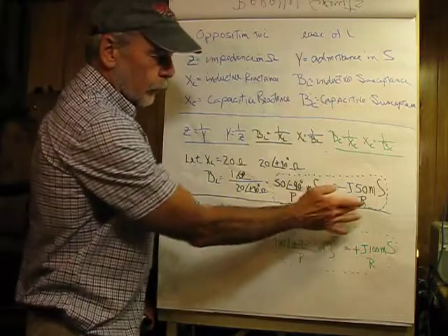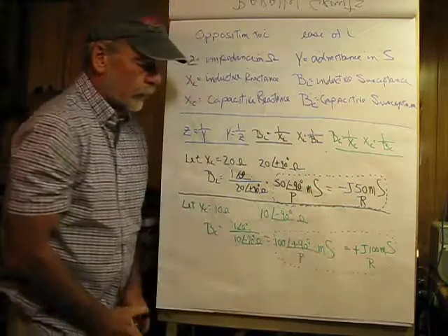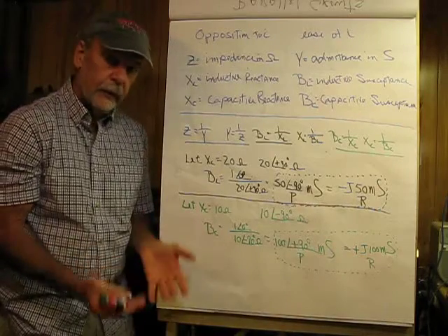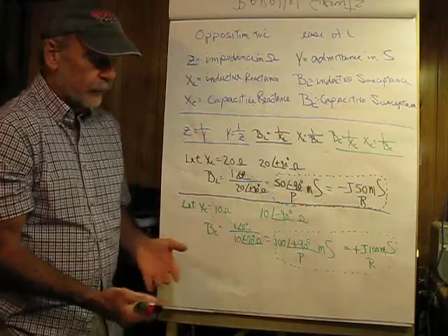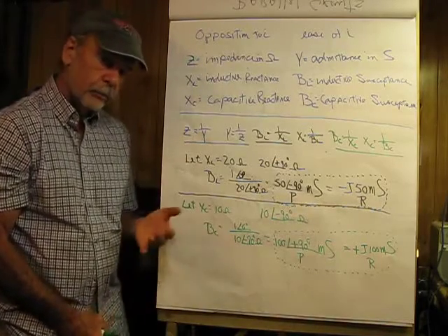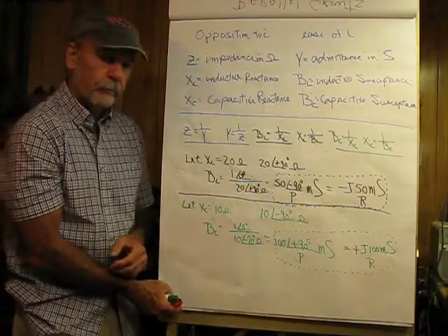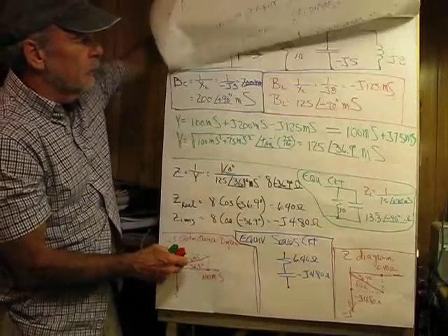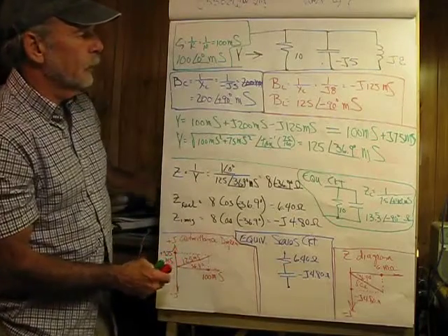So there's polar and rectangular for both of these, and it's up to us to figure out what we want to do. If it's adding and subtracting, we want to use rectangular. For multiplying and dividing, it's easier in polar form. So let's get into an actual circuit here.